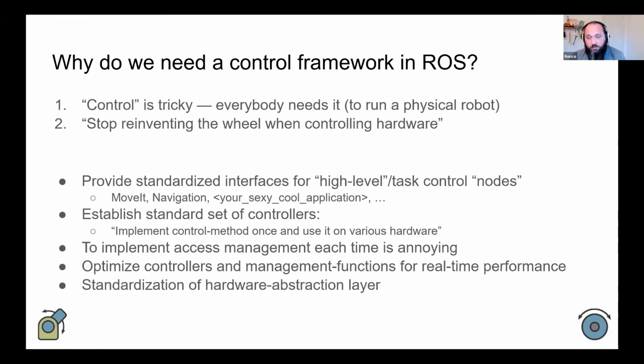By real-time safe manner, I mean, if your robot is a little bit more complex than an Arduino, you will probably use a CAN bus or EtherCAT or something more advanced that will not really allow you to do ad hoc communication scheduling, but you're going to run at, let's say, a fixed 200 hertz, for instance. So soft real-time safety is pretty important when it gets to robot control, especially, for instance, when you're running a biped robot, a humanoid biped that very actively needs to work to not fall and destroy itself. So that's a little bit of motivation here.